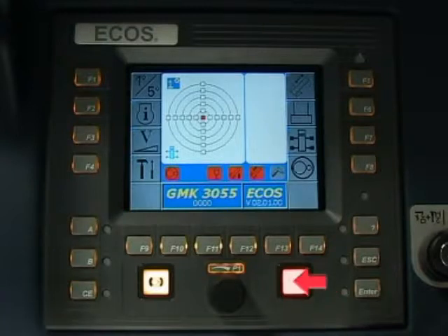This warning lamp indicates the status of the hoist limit switch. The lamp is on if the hoist is shut down by the hoist limit switch. The lamp flashes when the hoist limit switch has been triggered but shutdown has been bypassed. This rotary knob allows input values to be changed in the relevant submenus.